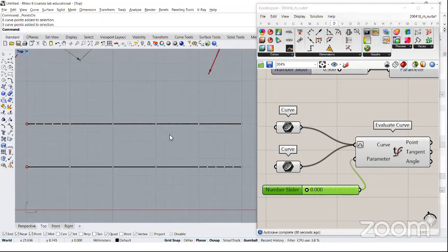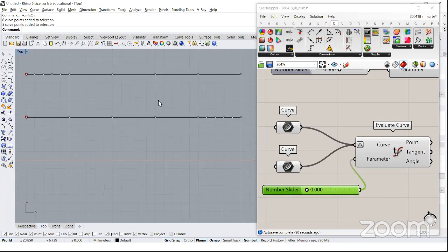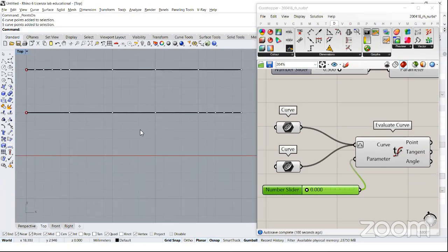There are many considerations about this particular situation. One of them, and this is the only one that I'm commenting on, is that McNeel itself in its manual recommends that, when you work with sweep 2 rails, the 2 rails have the same topology, more or less. Why?